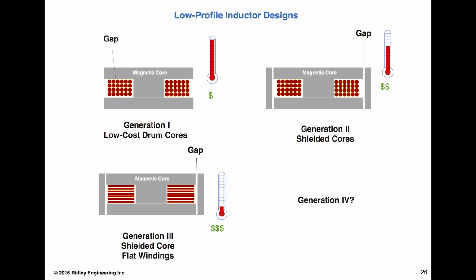The promise of GaN was that we're going to switch so fast that everything's going to shrink and practically disappear. The reality of topology development, and not to be too much of a downer on it, is that a lot of the topologies we're doing these days, we don't really care how fast it switches because we're going to zero voltage. So the anti-parallel diode of a FET is conducting before we turn that FET on.